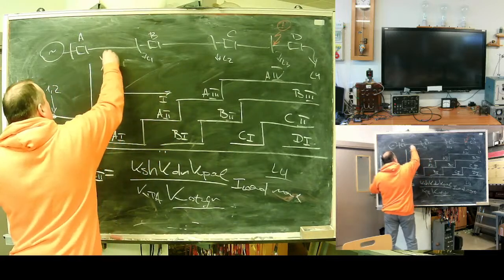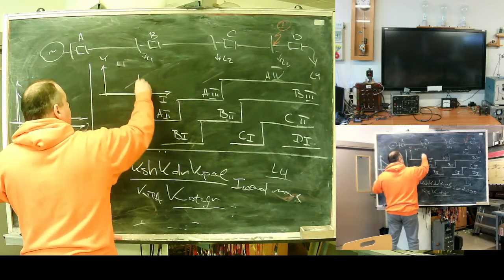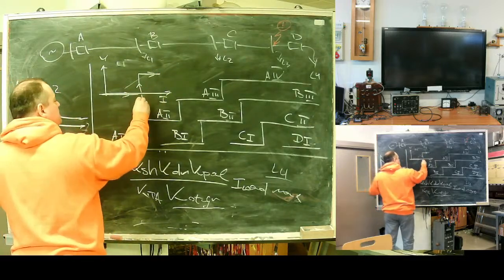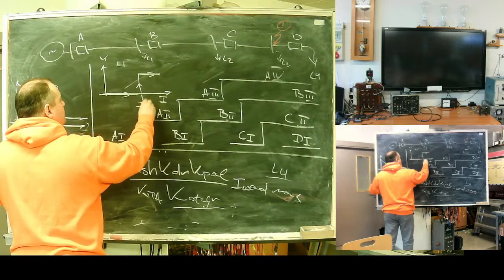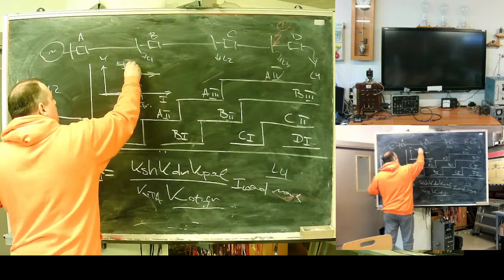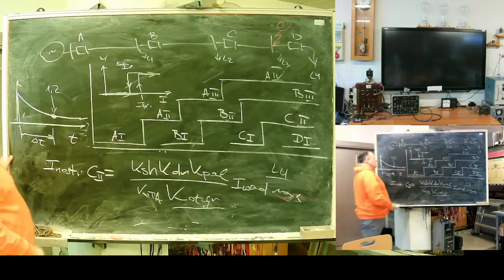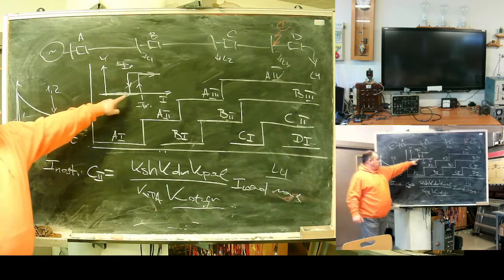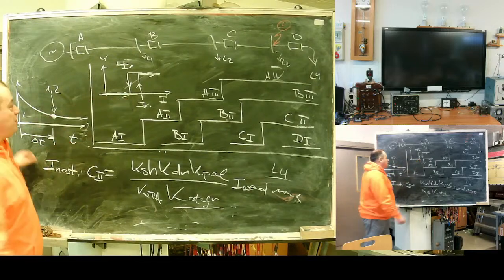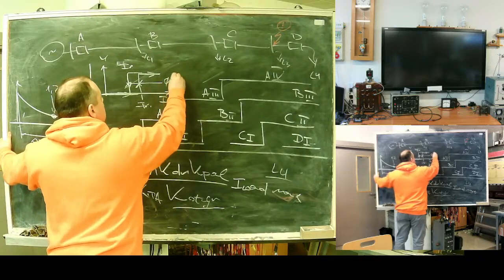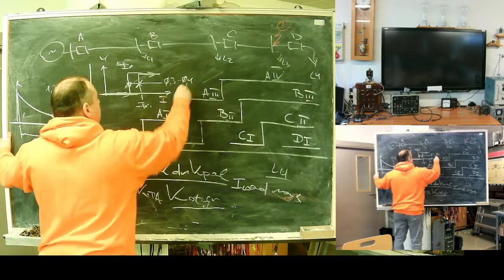It appears like this. Current output. If it increases, this is I trip. When it decreases, I return. Return coefficient or factor of hysteresis. Well, what is hysteresis? The factor of hysteresis for an ordinary relay may be 0.3, 0.4.